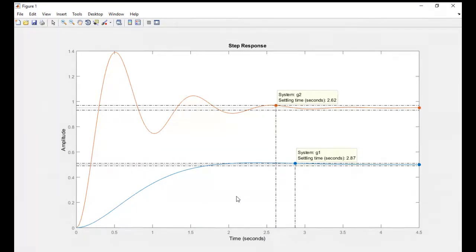Yes, sir. I was saying, for instance, if you tell it to go a certain distance, it will go over that distance and then come down. All right, I'm happy you said it because you were saying earlier that you don't know if it's significant. Having said that, do you deem it to be significant? Yes, it is. These overshoots could mean it's going to crash into something that is probably above it. If it's in the house, or in an arena you're flying, or in a closed space, then clearly that looks like over 40% overshoot. It is going to end up in the ceiling. So yes, it does matter.